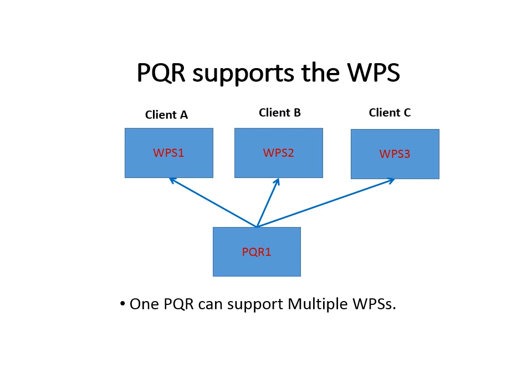I used to work at a place where there was probably 20 different WPSs that were just all slightly different, and it was for all welding carbon steel and using E7018, low hydrogen electrode. But you'd have a client come in and say, I want it to weld between this voltage and this voltage, and I want my WPS to have this cleaning method and this cleaning method. I don't want you to be able to use a grinding wheel on it. Use this special wire brush from Lithuania or whatever. It was some kind of requirement. So we would have a very specific WPS for that client and that client only.